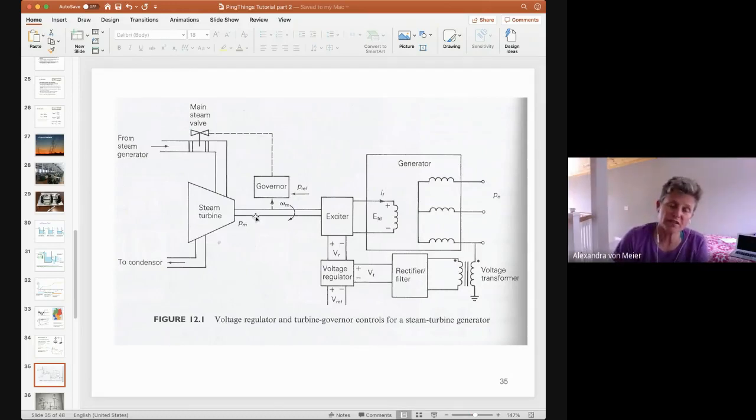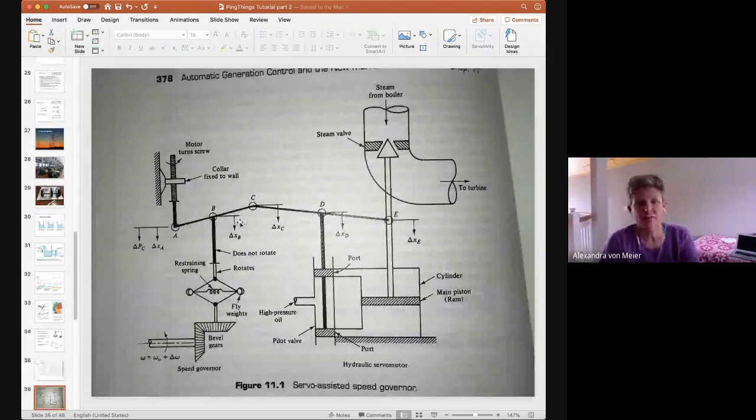There's a whole separate system for controlling the voltage magnitude at a generator bus. Someone asked about this in the Google Docs, and I began to say that the voltage magnitude is regulated by the reactive power output, which is totally not obvious, and we can come back to that in another session. So we should assume the voltage magnitude stays constant, and all we're dealing with, with real power, is the angle and the frequency.